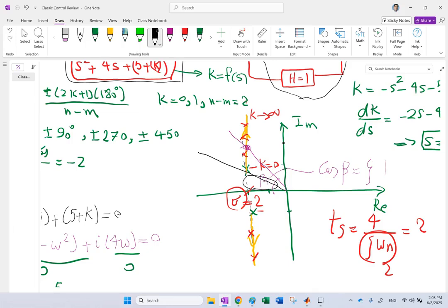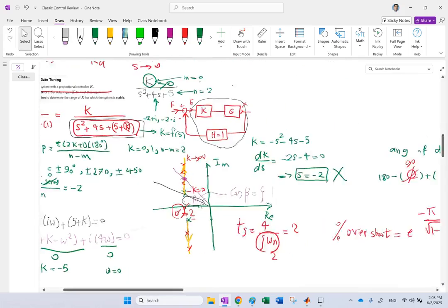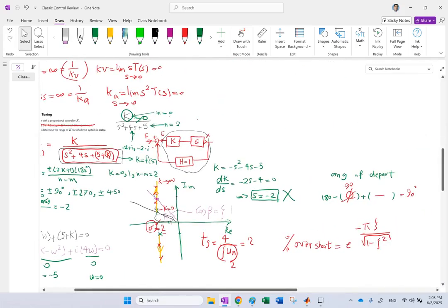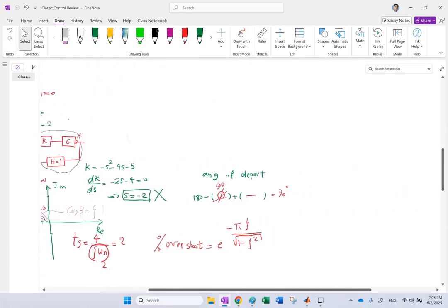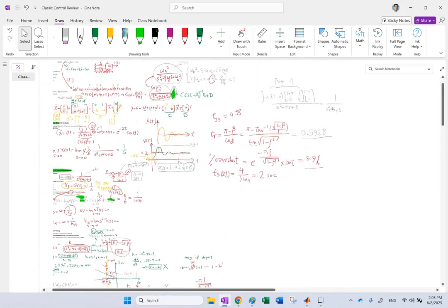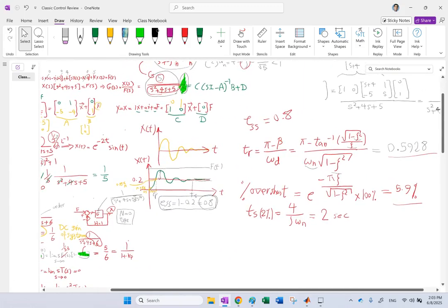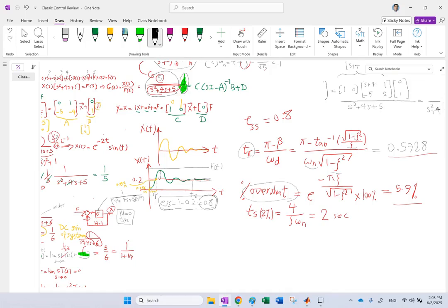I can make it bigger. And you might say, why would you even make it bigger? What's the point? Having a bigger overshoot, what does it give us? Well, you can achieve instead a faster rise time, because rise time and overshoot are typically the opposite of each other. You can make the overshoot go up, and instead you can make the rise time go down. Okay, so can I achieve that?